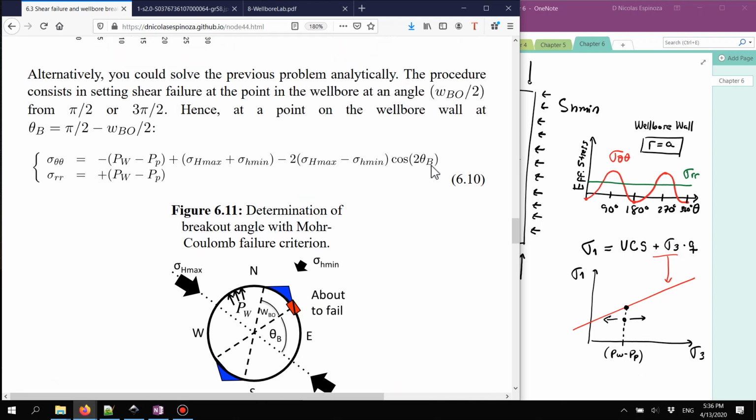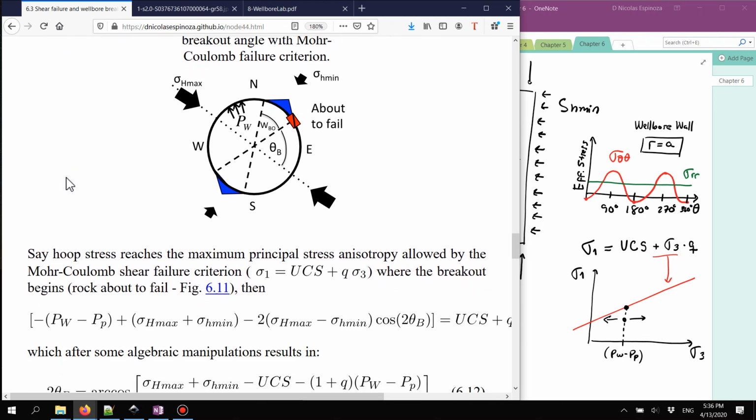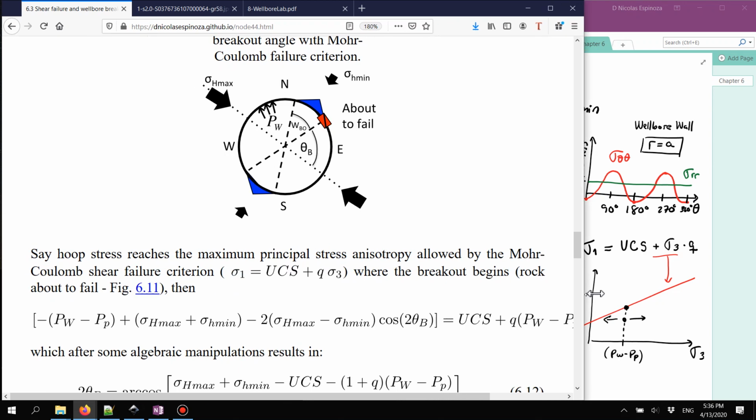In this case, we have left the component theta available to calculate the condition of stress at a given angle theta from the direction of the maximum stress. I'm going to set sigma 1, the maximum stress, as sigma theta theta, and sigma RR to be the minimum principal stress, sigma 3. When I do that, this is the equation. Let me expand it a little bit.